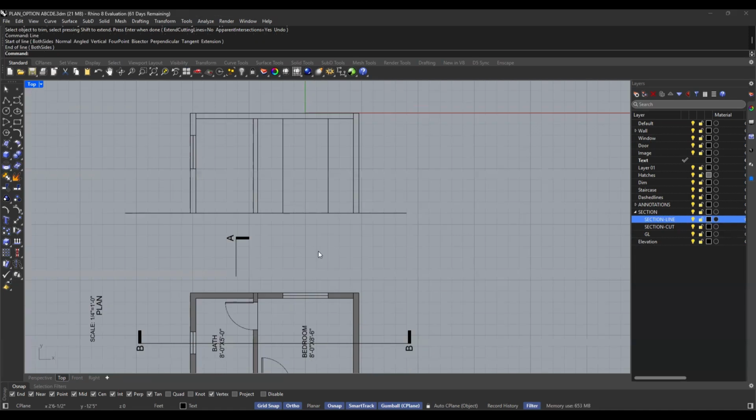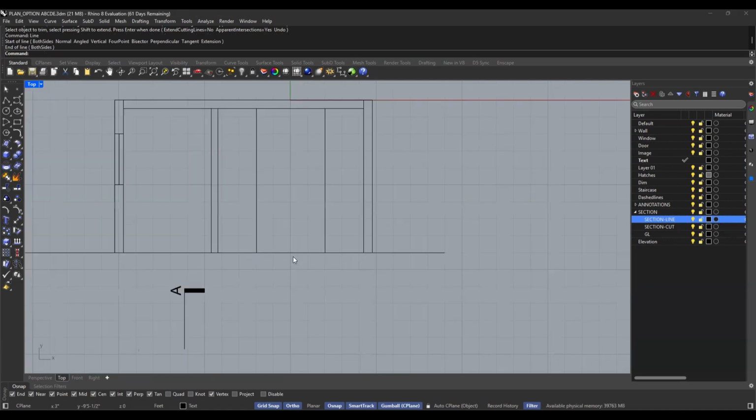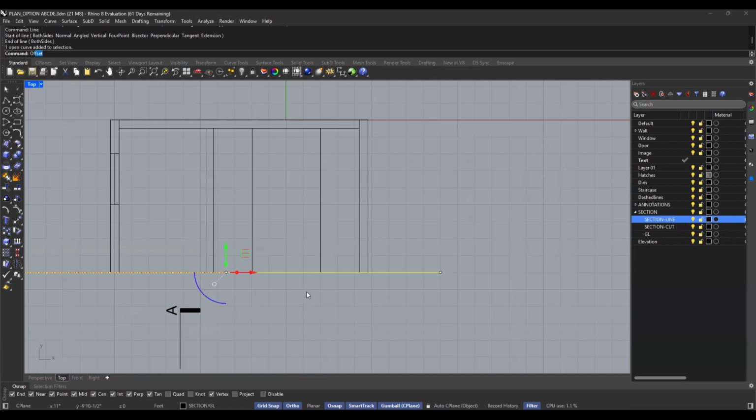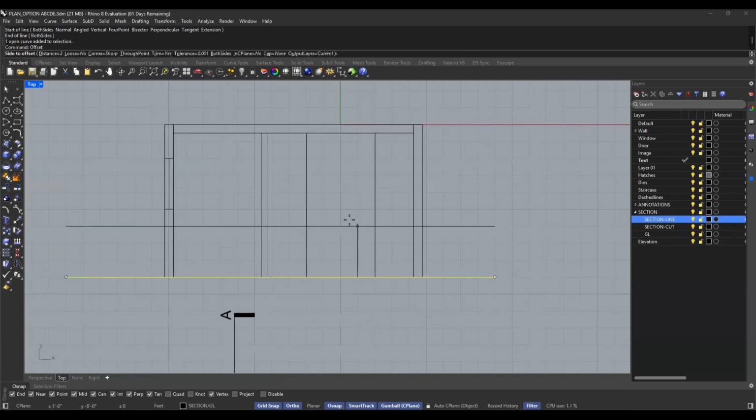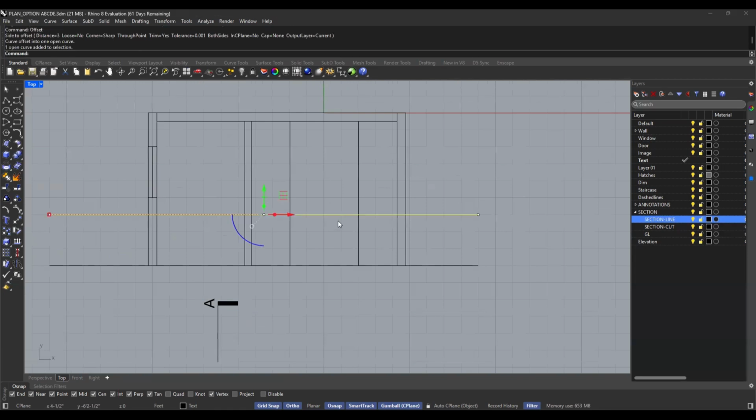And so we have another window. It's in the bedroom. So again, type offset and ceiling height. Let's just do 3 feet and hit enter. And the height, it could be like 4 by 3, right? So I'm going to say, okay, do 3 feet for the height.